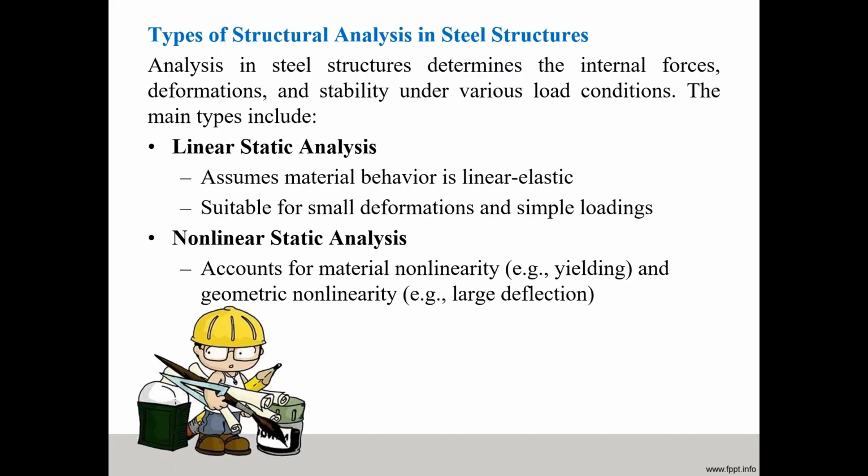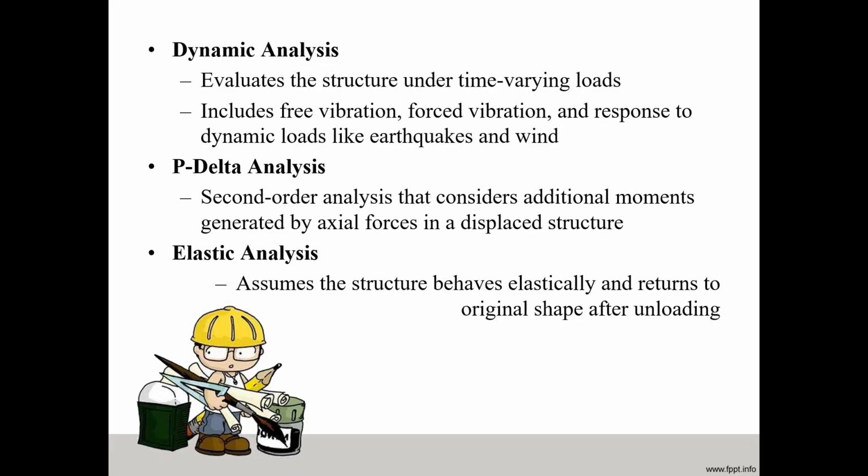On account of material non-linearity, for example yielding, and geometric non-linearity, for example large deformation, we use non-linear static analysis. Then dynamic analysis evaluates the structure under time-varying loads. It includes free vibration, forced vibration and response to dynamic loads like earthquake and wind.